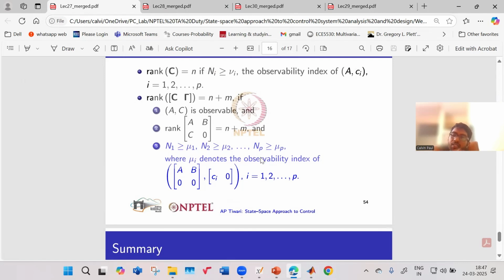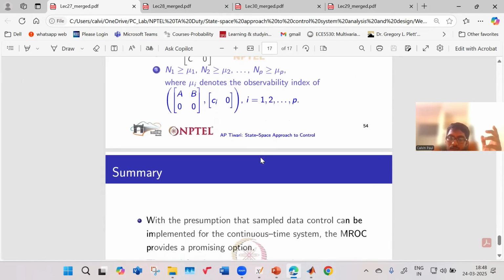We will need a very high power ADC, and we have to store that data, so it is not always feasible. So we have found that the minimum number of samples we need to take is 3 for both output 1 and output 2. And remember, our input being applied to our system is a discrete input, provided from the output of a zero-order hold.